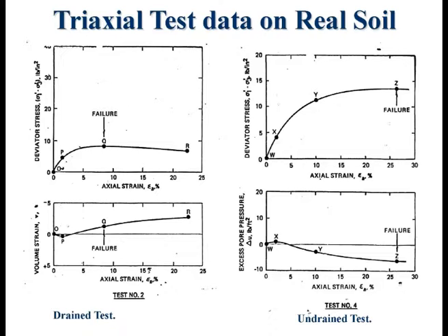linear elastic model is insufficient for a lot of soil. I won't say it is insufficient for all soils. But if you have a piece of rock, I think you have good reason to say it is going to remain elastic, because for the stress level that the soil can apply to the rock, if it's a fresh piece of rock, I think it will be fairly elastic, you know.